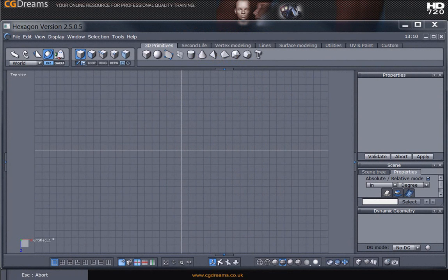3D guides in Hexagon allow you to work more precisely in both increments and distance measurements, using the background grid to constrain to. Now there are several tools in Hexagon that automatically use this 3D guide system, like the snap, align or symmetry. As mentioned in previous chapters, you can hold down the Shift key to aid in locking to a certain vertex on your geometry in your 3D scene.